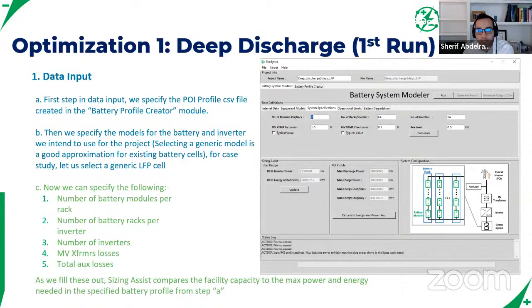But what you probably need to account for is that there are custom solutions out there. It's not just about what the inverter OEM is doing, but also there are a lot of battery integrators out there that put together really sophisticated fusing schemes to allow higher duration systems. Definitely not anywhere near the 100-hour duration system you have here, but when you start getting into 6-hour, 8-hour and beyond, you start getting into a need for more sophisticated systems, especially if your inverter has a common DC bus.